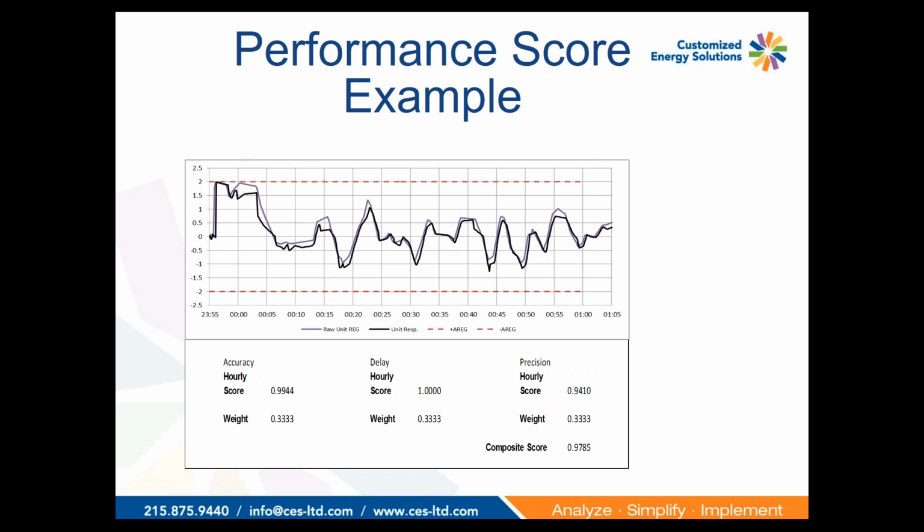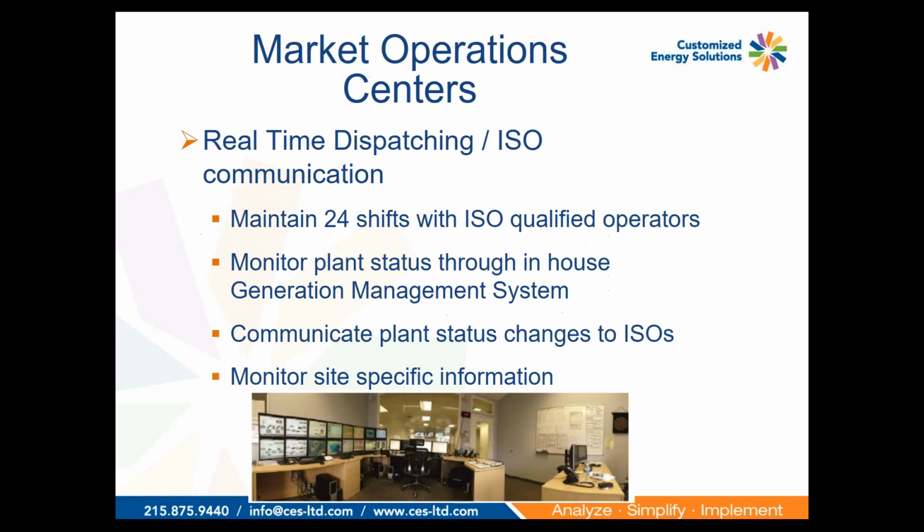And again, all the data that they're using comes from that telemetry stream, making it very important to make sure that there are not any delays in that telemetry stream or any latency between the facility and the ISO. Because that can significantly impact performance score. Also, it means as you're implementing the telemetry, you want to be using as few components as possible between the ISO and the site to limit any time delays in handing off points between those components.